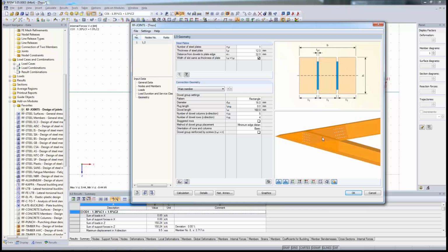Now, if I come to the priority that I told you before in the masked nodes and members, it's not so economic to have the top girder aligning to the bottom girder, because it gives pressure to the bottom girder, and pressure rectangular to the grain is not so good with timber materials. Therefore I want to change it and let the top girder go through,